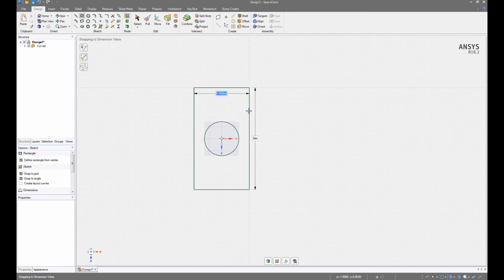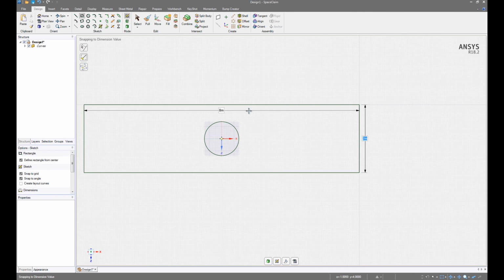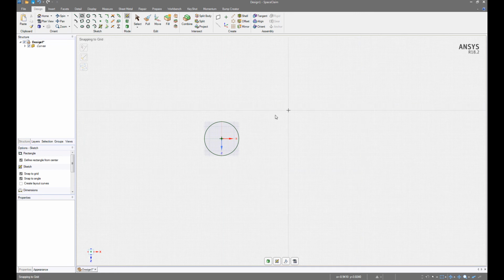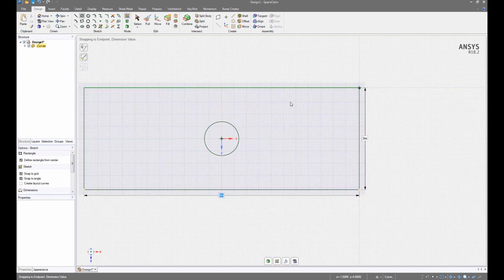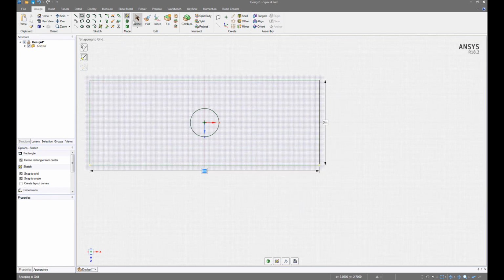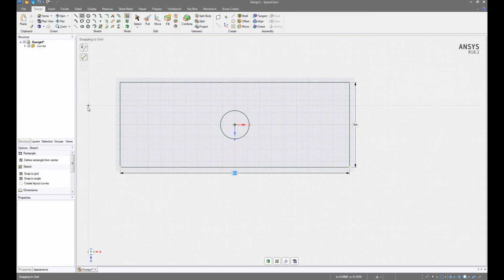We'll start with a 3 meter gap, maybe 2 meters is fine too. And in this section, we'll make it 8 meters. Let's try that again. So 3 by 8. Okay. We want to exaggerate the downstream section. So let's say the flow goes from the left-hand side to the right-hand side around the cylinder. We expect wake and vortex shedding behind the cylinder, so we want to have enough resolution over here to capture that.